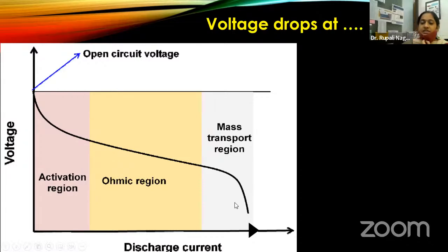when the battery is giving out very low discharge current, you're actually forcing the battery to undergo what is known as mass transport. That means the material will physically start leaving the electrode materials, and you're causing physical damage to your battery. Of course, we can't see it from outside.